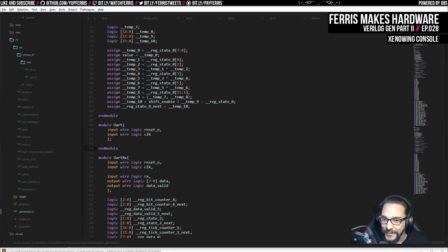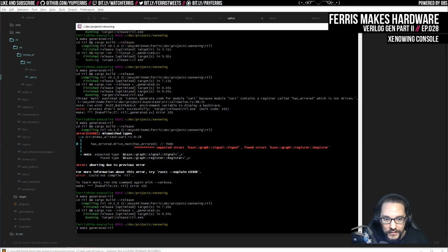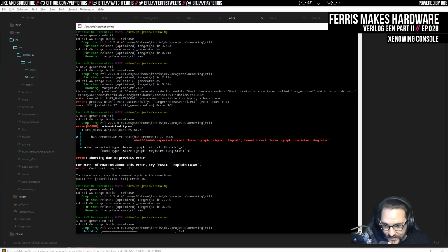And now, oh, it was optimized away. That's funny. So it's validated and it generated code, but it didn't do anything. So I guess we'll have to make that do something later. But actually, we are going to want to output this. So let's do that. m.output, and we're going to say has errored, and that's going to be has errored.value anyway. So this actually we do want. And then we should see the register there.